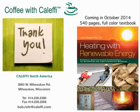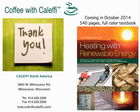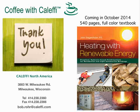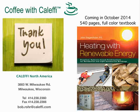In a deep southern climate where you've got a long cooling load, I would expect the geothermal system will outperform on an EER basis the air source system. I ran just a heating load analysis, but in a situation where you've got both heating and cooling loads, the software from the manufacturers that I use will do both of those, so you would run a year-long basis.